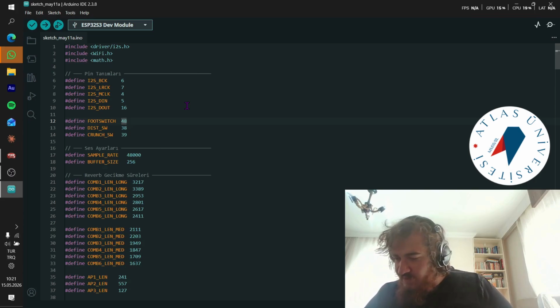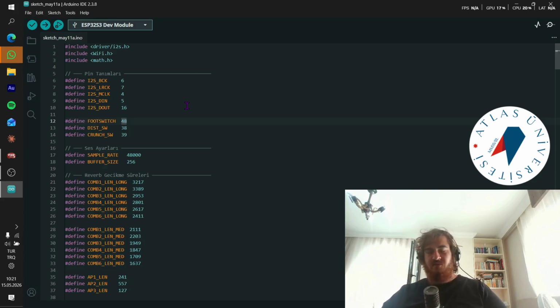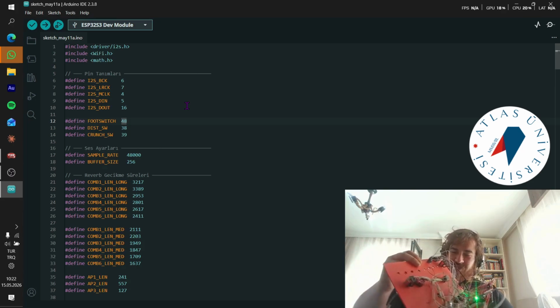Besides that, I tried to use CD4051BE as a multiplexer because I was trying to utilize 8 potentiometers and a 12 location rotary switch. But I think it's because of the complexity of the circuits. As you can see here, it's such a mess.